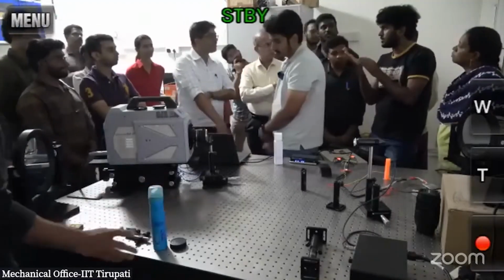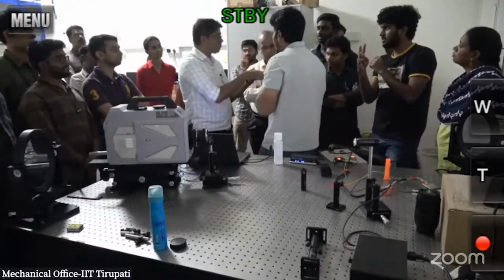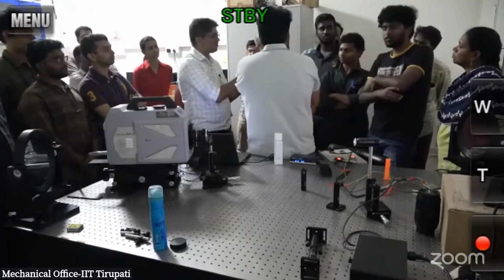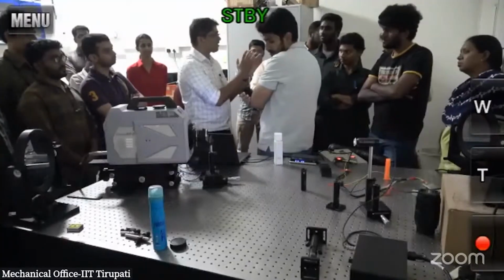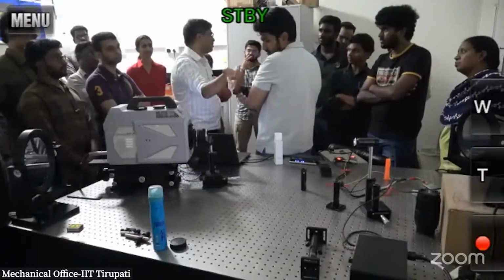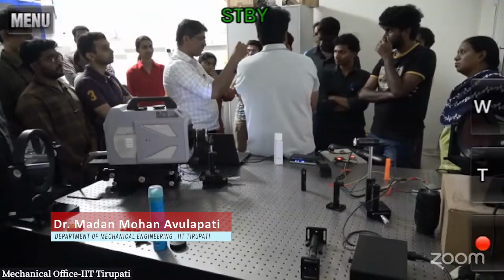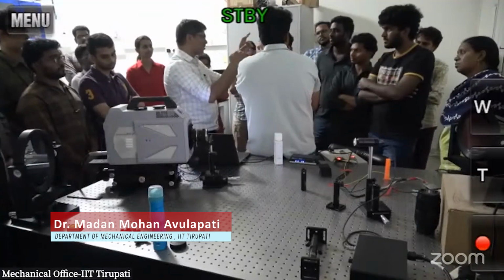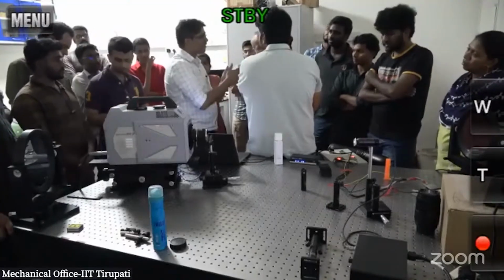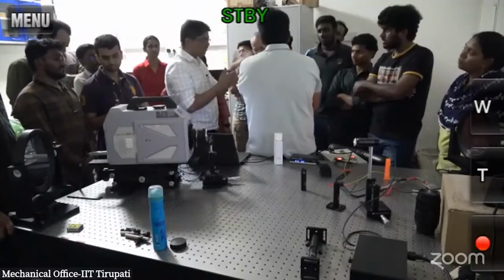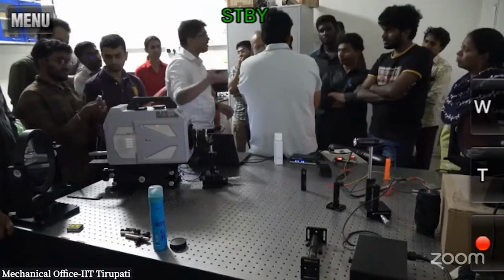If there is water evaporating, that will show differently. The Schlieren tool will show the density gradient. Like the other time we saw with the deodorant, when there was no flame, the density gradient was not much, just a tiny gradient. The moment there is a flame, you have a one or two order of magnitude difference. Then you can clearly see. Even if you have sweat evaporating, it will show, but maybe you need to increase the sensitivity even higher.